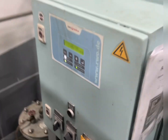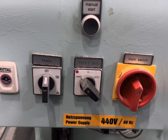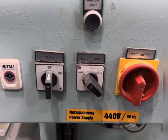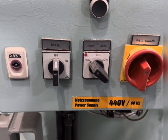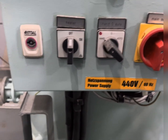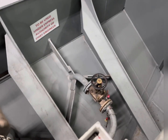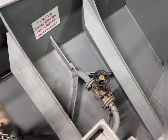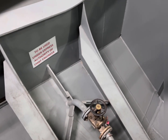So guys, here you can see that the oily water separator is running in the manual mode. That is the code D, non-automatic operation of OWS. So what we have to do, we have to prepare the line. We have to open the valve from the bilge holding tank, open all the valves near the oily water separator, open the overboard valve. This is the overboard valve. Open the valve, break the seal and record it in code I of the oil record book.